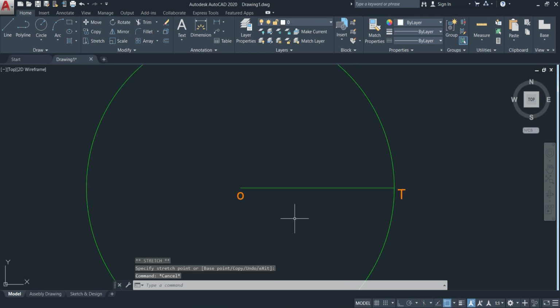Alright, now once we have those in place, the next step is that we're going to divide this radius here. So basically we're going to be dividing this line here. You could decide to divide this line into 4, 8, 12, similar to other engineering curves. The option is yours. You could go 12. The more points you have, the smoother your curve is going to be. I think for this I'm just going to make it 8. So I'm going to divide this line into 8 equal parts.